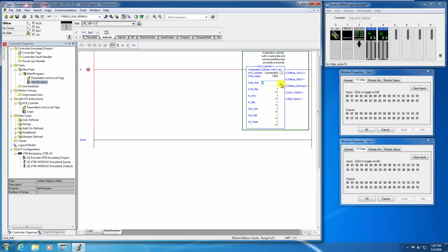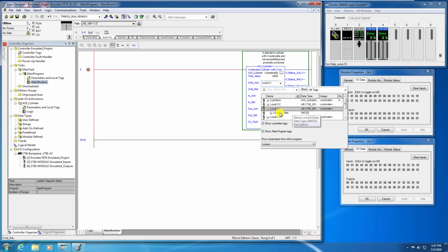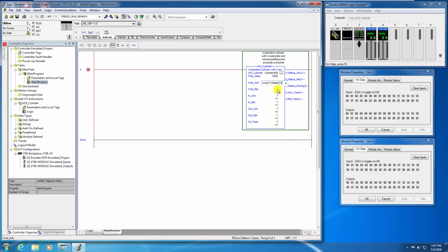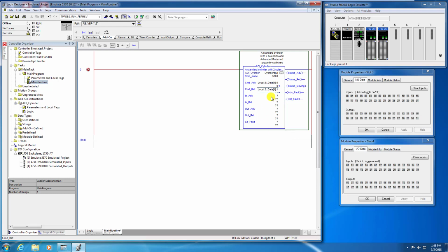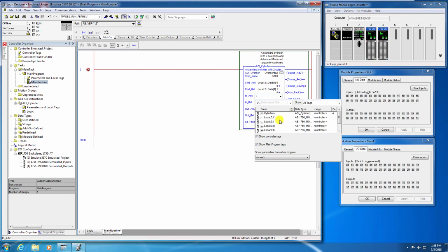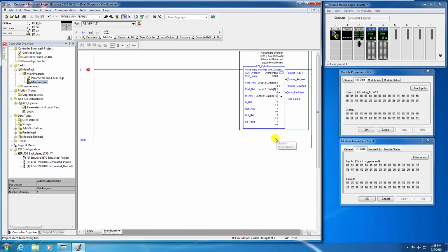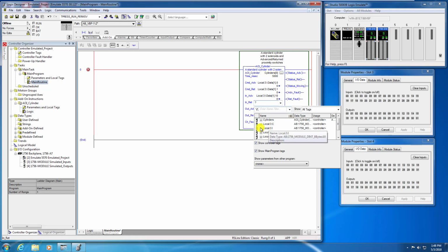All right, so let's start picking off some bits. And data, remember we've got to use array 1. Let's make it the first one. Perfect. So my push button for advance is going to be the first toggle here. Now to retract the cylinder, let's make it the next one, 1. And now we're going to simulate some proximity switches on our cylinder. Let's make the advanced input, let's say it's wired into, we used 0, so let's use 10. So 1, 0 is going to be the advanced switch on our cylinder, and we'll use 11 for the retract switch on our cylinder.